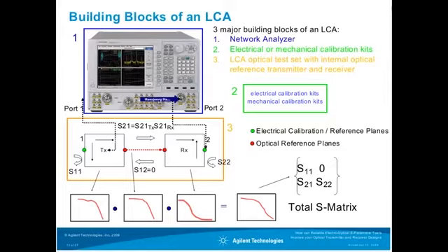And if you have a device under test, which is, for instance, a receiver, then you always have two conversions. You have one conversion from the electrical domain to the optical domain, and the optical domain to the electrical domain. Here again, we have the concatenation of individual responses of a transmitter and a receiver.